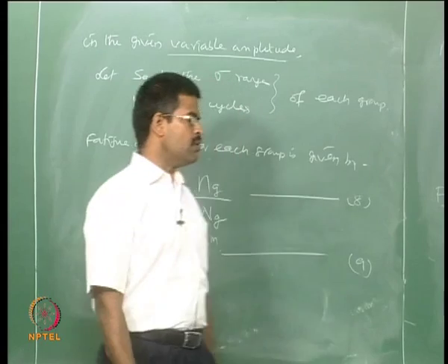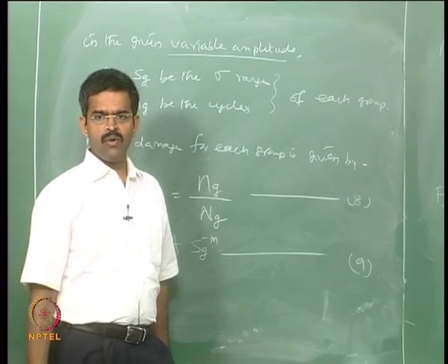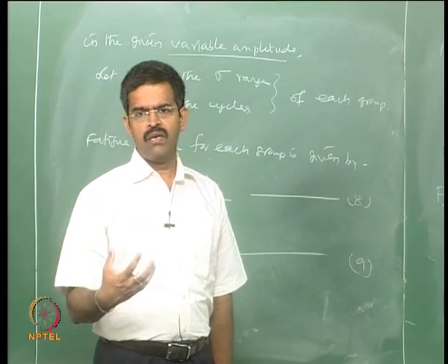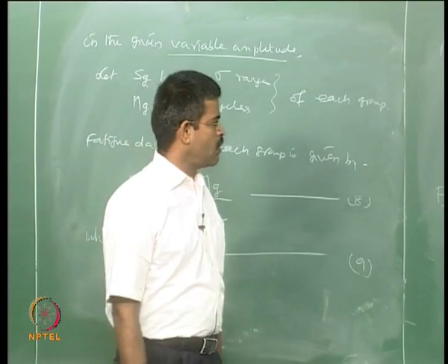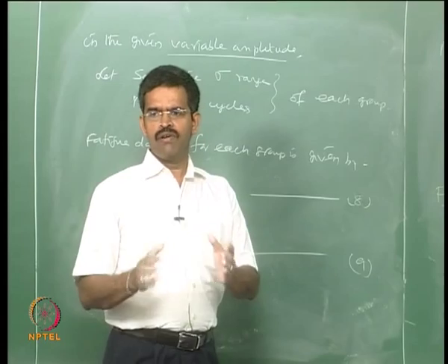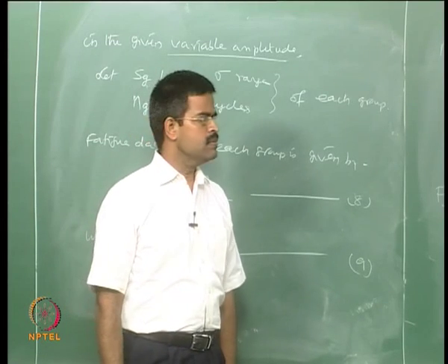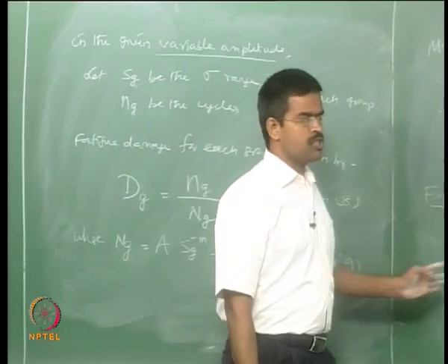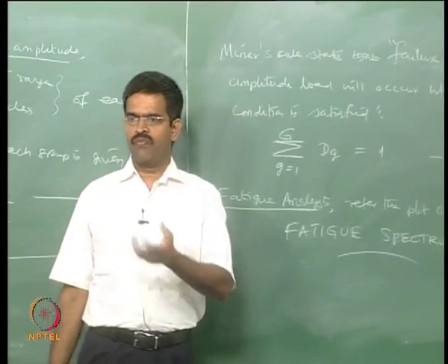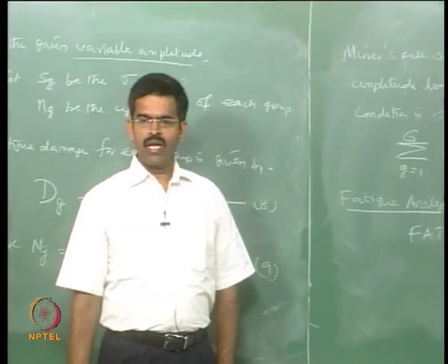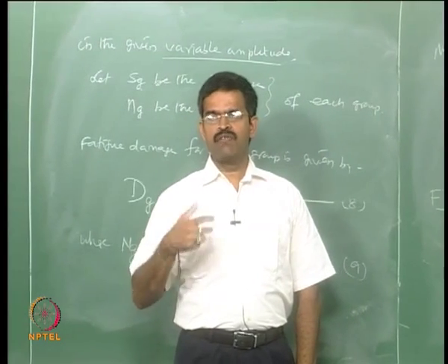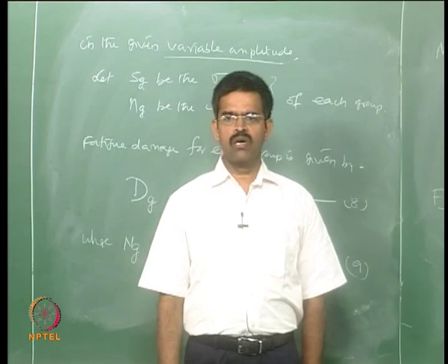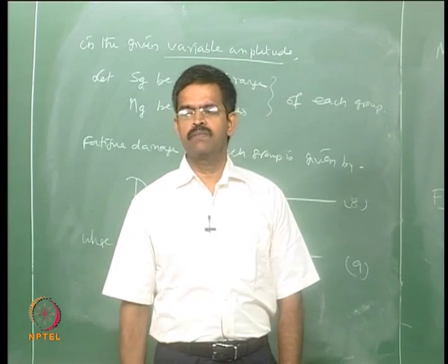Therefore, SN curves can be used only as a preliminary analysis of fatigue failure or fatigue damage, essentially to estimate fatigue life. But in reality, in marine structures we have a mixture of variable load effects, whereas SN curves are plotted in a specific manner on a type of specimen where the forces remain essentially tensile stresses.